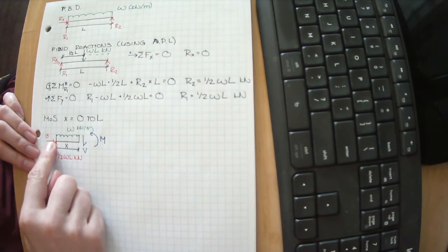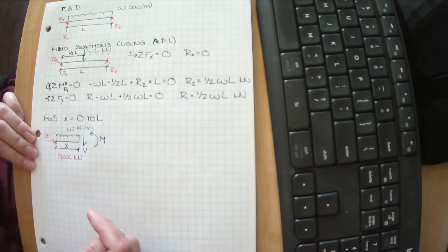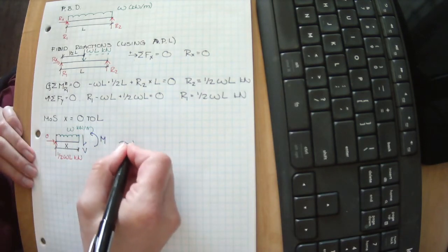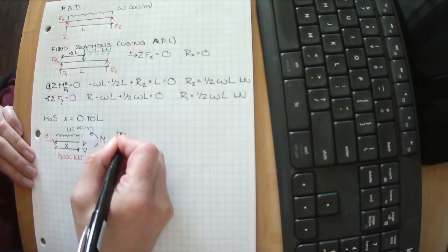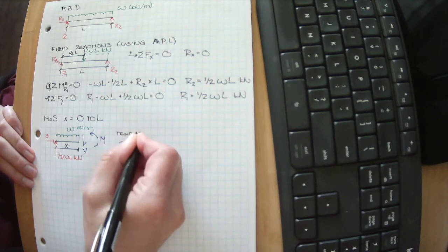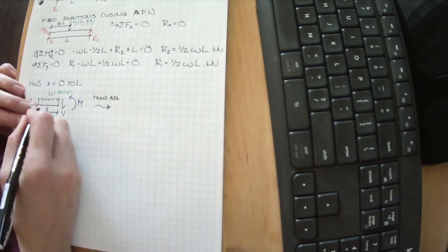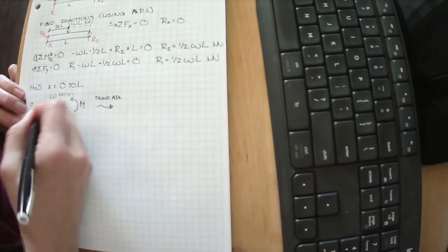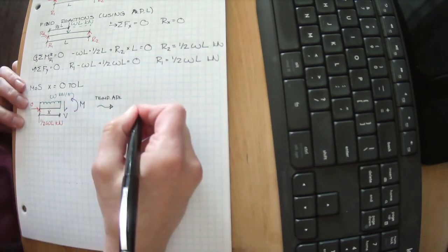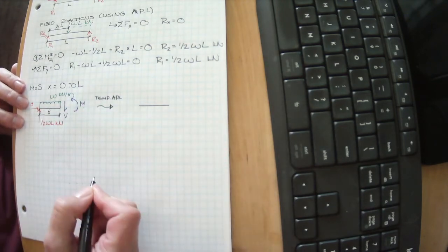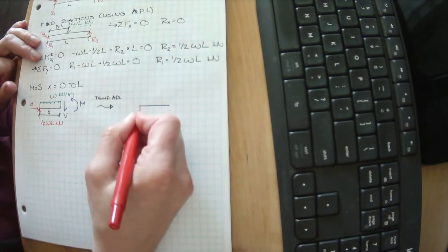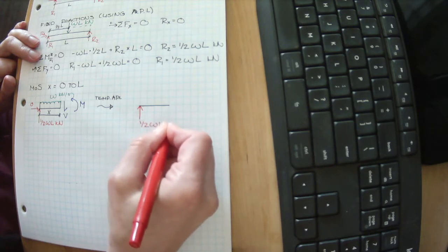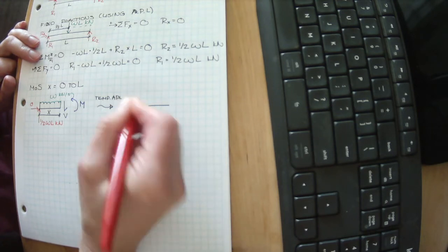Solving for a uniformly distributed load on something is a bit of a pain. Let's use a temporary analogous point load to solve this problem. So let's just redraw this with its own temporary analogous point load of this free body diagram. Okay, so we have our member there. We know our reaction doesn't change. This is still 1/2 WL kilonewtons, and that's still 0.